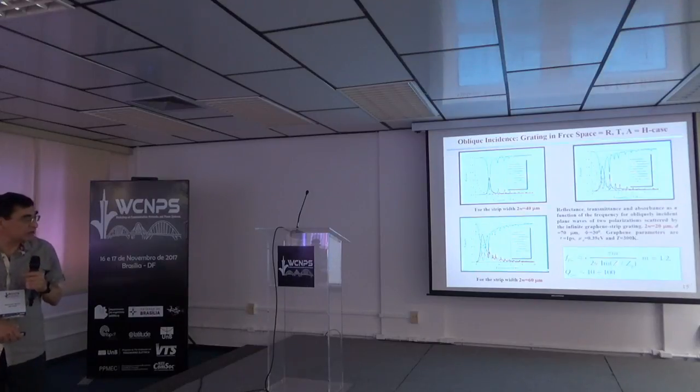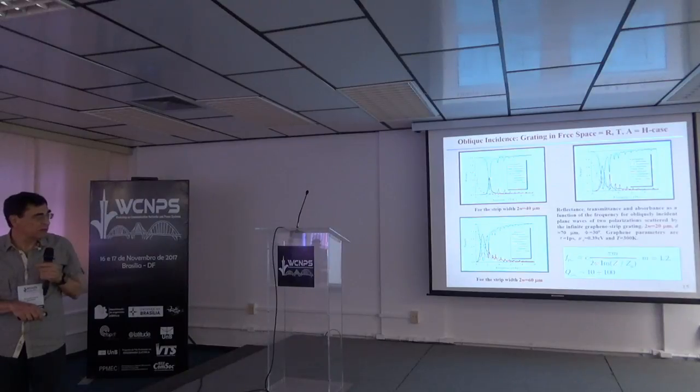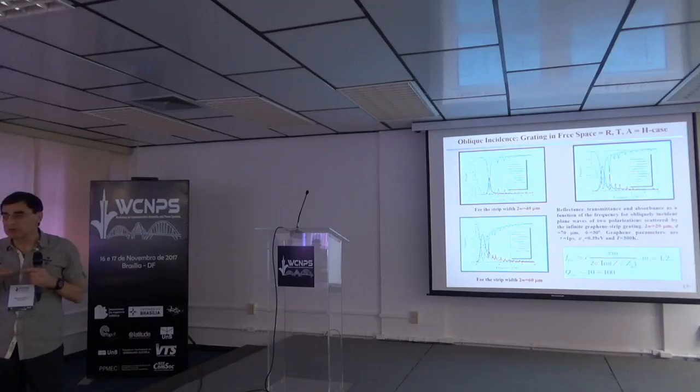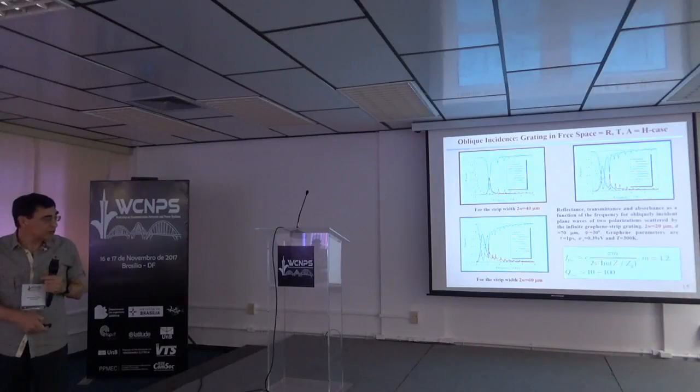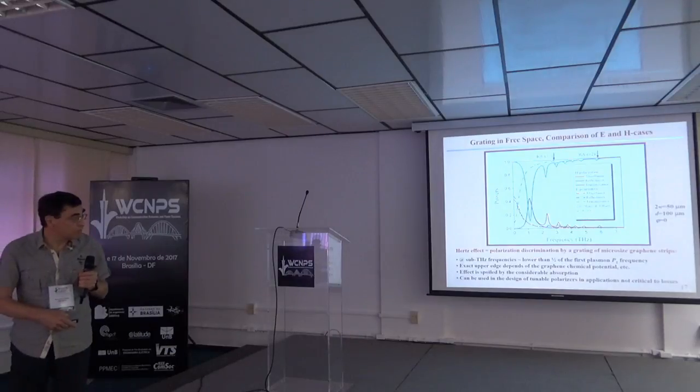The frequencies of these resonances in the first term, in the main term, are given by this formula. They depend only on the width of the strip and the surface impedance, but they do not depend on the period of the grating. Therefore, we can see that each strip resonates separately. The coupling between separate strips is negligible. Further, one can see that this coupling becomes more or less significant only if the strips are separated by the gaps measured in several nanometers. The quality factors of these resonances are not very high, but not very low, between 10 and 100 approximately. Okay, so this is the free space case.